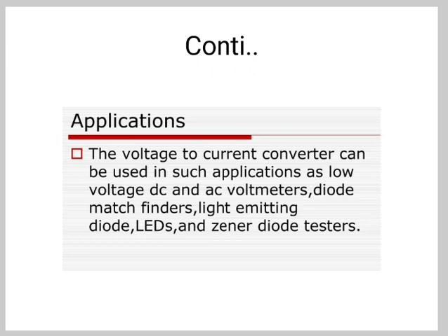So, when the switch is in position 2, the circuit becomes a Zener diode tester. This circuit can be used to find the breakdown voltage of the Zener diode. The Zener current is set at a constant value by Vin and R1. If this current is larger than the knee current of the Zener, then the Zener blocks the voltage.